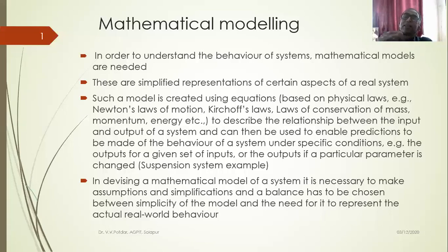So this shear stress tau is proportional to velocity gradient, and its constant of proportionality is mu, that is coefficient of dynamic viscosity. So tau is equal to mu into dou u by dou y. If I solve it for mu, what I'll get?